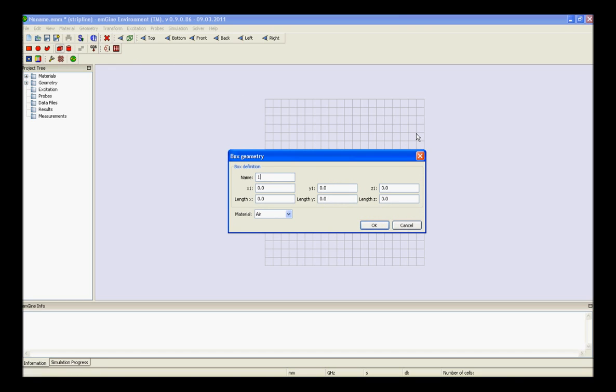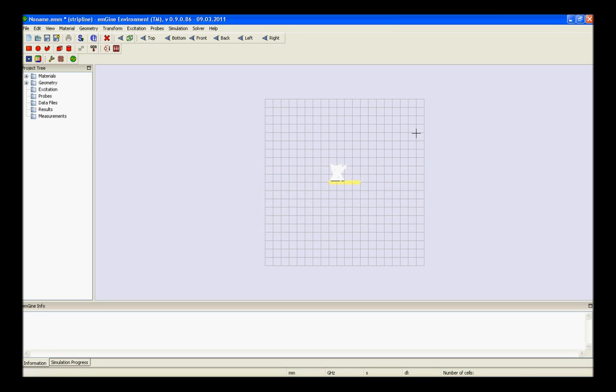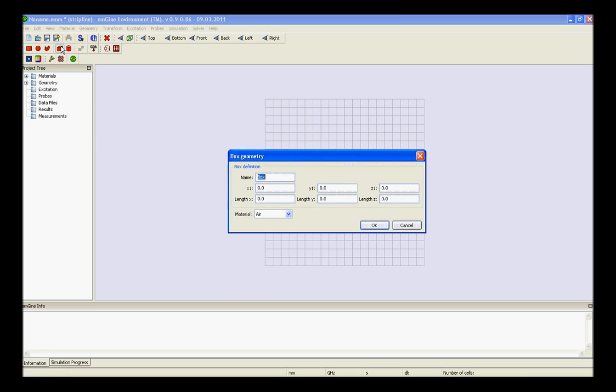Again do the same process for creating a substrate, because this strip line is sandwiched between two substrates of the same dielectric material. For this purpose, again go to Geometry, select Box and in the dialog box give the transversal coordinates. Select the new_material as the material for the substrate from the material drop-down list in the brick creation dialog box and press OK to finally create the substrate.